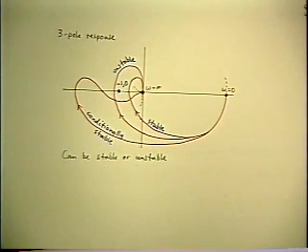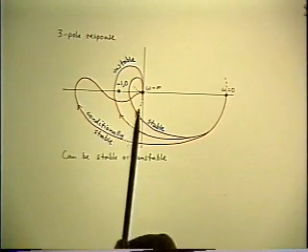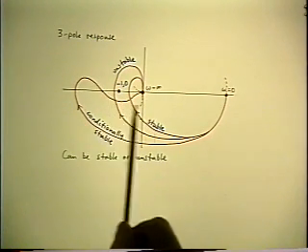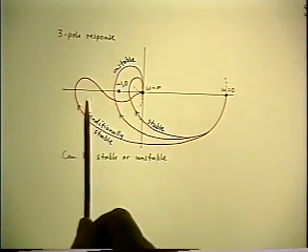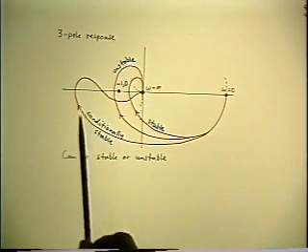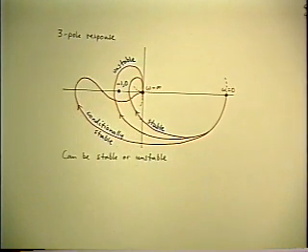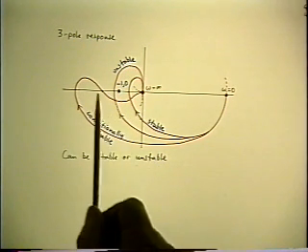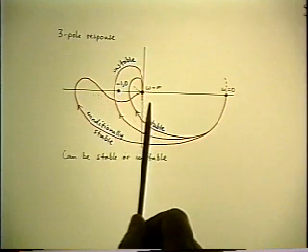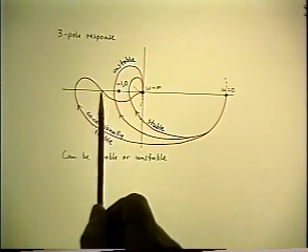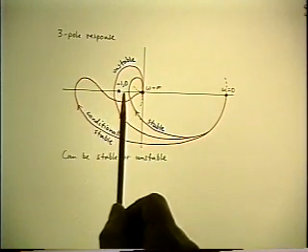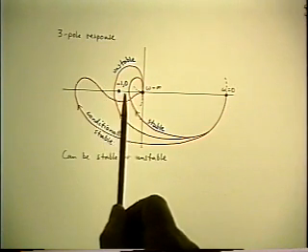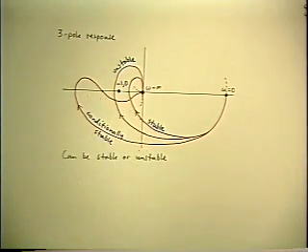And that may be all right, but the problem with it is that if it's stable under a normal configuration, such as the one I've shown here, it could go unstable at lower values of gain, because a lower gain would make the contour get smaller, and if it gets smaller in such a way that this loop went around -1, it would go unstable at a smaller scale. Now that's hazardous,